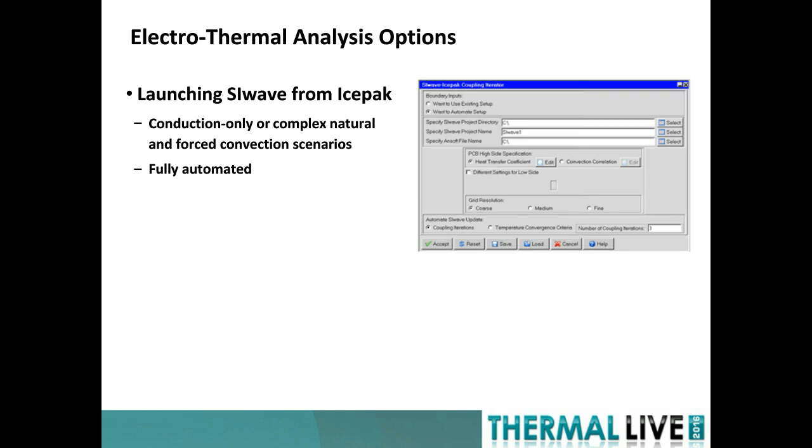They're usually specified in terms of a Nusselt number versus a Reynolds number, and you can determine what the heat transfer coefficient is for that convection scenario. So two options: just run the CFD analysis, don't worry about it, or do a little bit of homework and find what the appropriate heat transfer coefficient would be in that case.